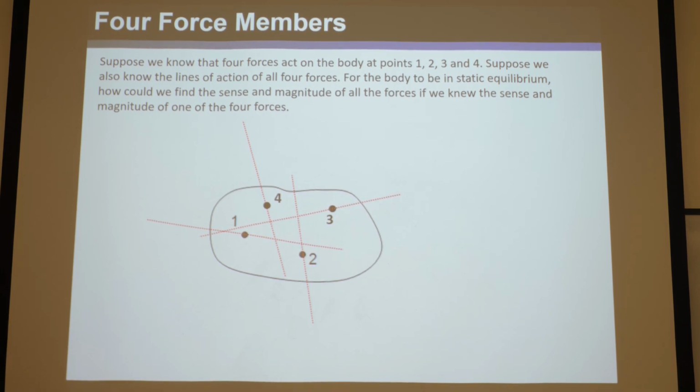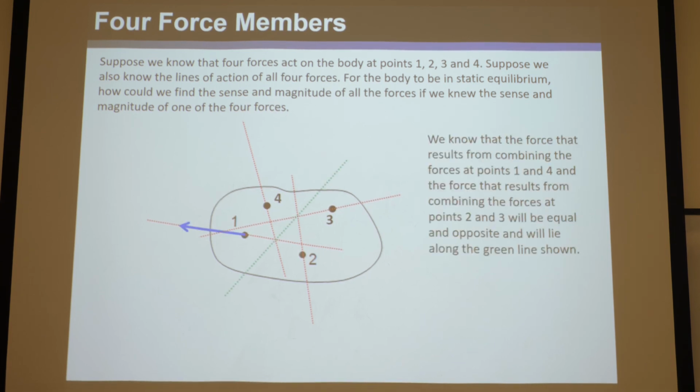So there are different ways to think about it, but as long as your logic is correct and you use these force loops that equal 0, line things up head to tail, and treat things as 2-force members and then 3-force members and all this magic, you'll get the exact same results, of course.